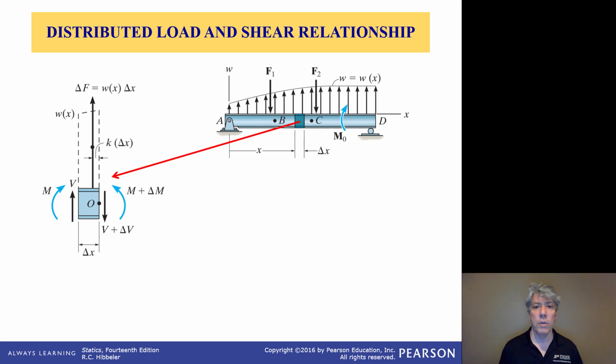So what kinds of loads can be applied? Well, of course, there are axial loads, but because of the pin supports and the roller supports that we have in this problem, and the fact that there are no external loads in the horizontal direction, the compressive and tension loads along the axis of the beam are not useful. They don't do anything for us.